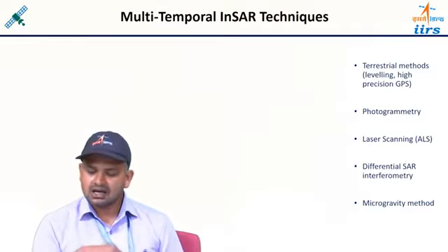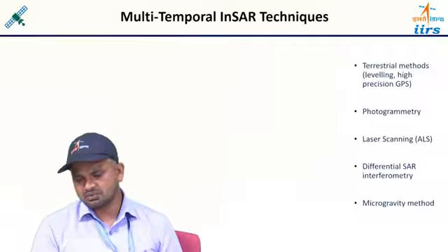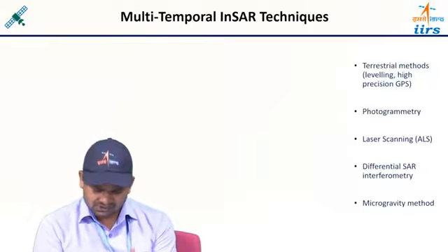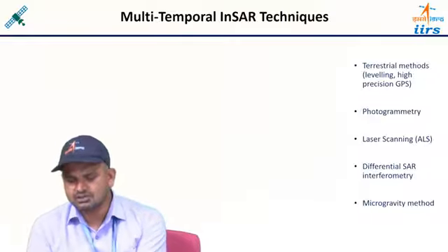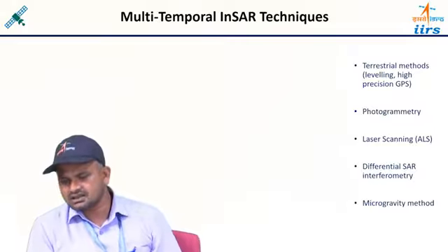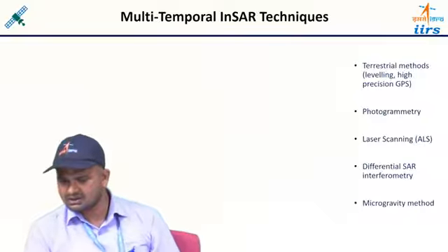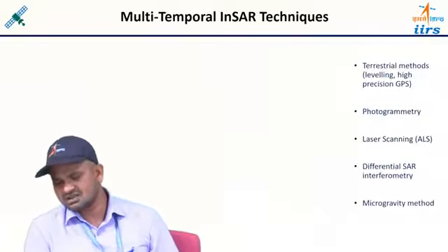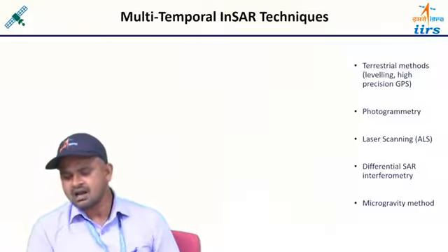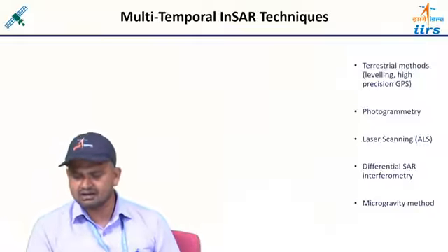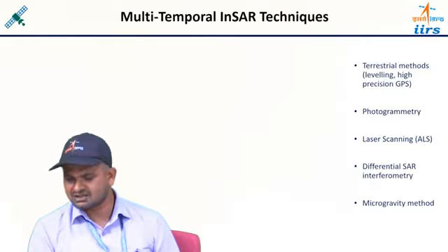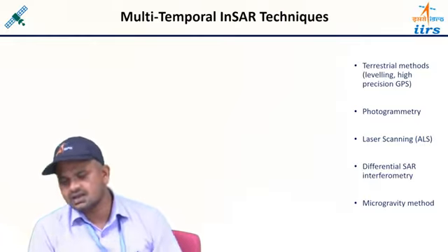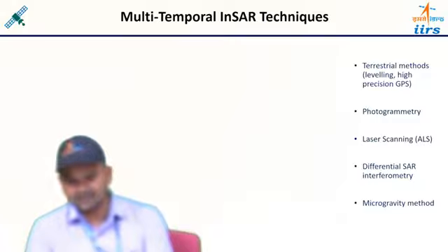And then, the accuracy level of the outputs we are expecting from differential SAR interferometry is almost matching the terrestrial methods like GPS or leveling, because the accuracy of the leveling or GPS technique is sub-millimeter, or you can say millimeter scale, and more or less a similar level of accuracy we can expect from the InSAR techniques, or rather the advanced versions of the InSAR techniques with modern advancements.